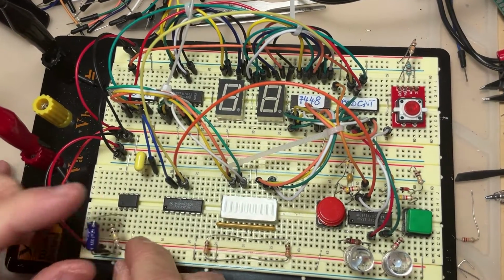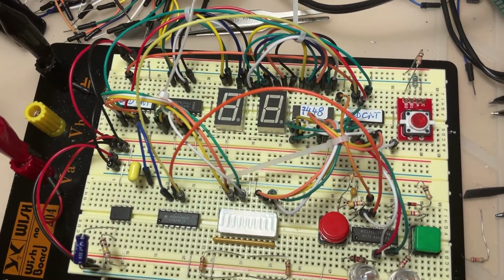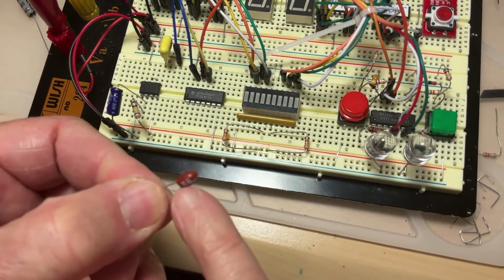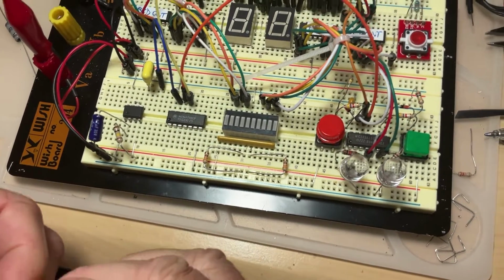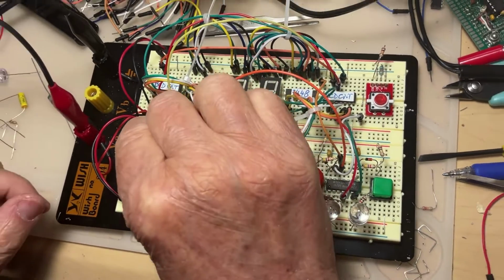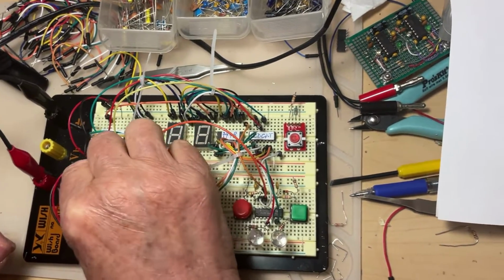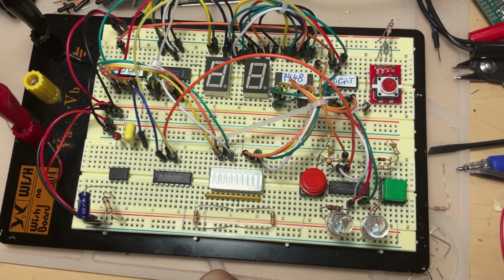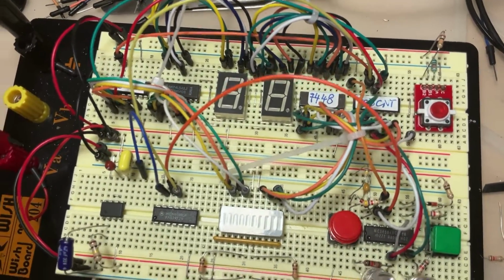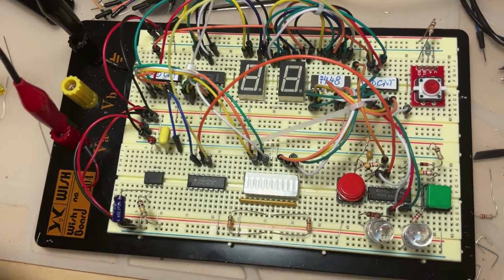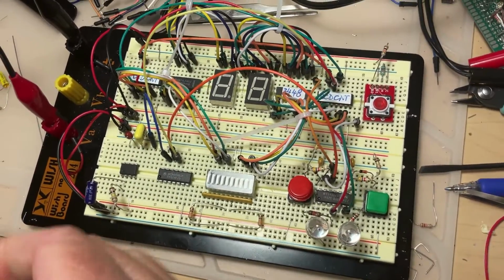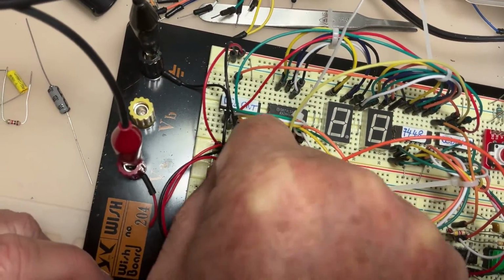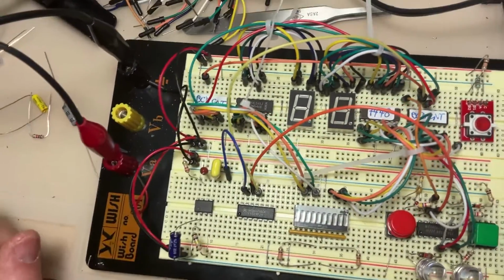This is done. Then the capacitor of 10 microfarads is going to be this one, exactly like the one before. It is going to be connected between pin 5, the pin 6 or 7, to the positive. And then I'm going to make it longer. I'm going to put a 220 kilo ohm resistor from the same pin here to the positive to charge it. Okay.